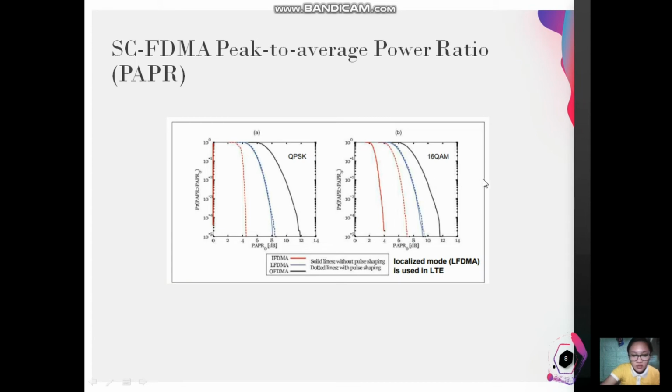In 2G and 3G, there is no filter definition. In LTE, this is open to the design engineers. LTE just defines in-channel requirements, for example, modulation capability measured within the EVM, and out-of-channel requirements, adjacent channel leakage power ratio, or spectrum emission, which need to be passed by the transmitter design. In this simulation, a root raised cosine filter was used with a roll-off factor of 0.5.